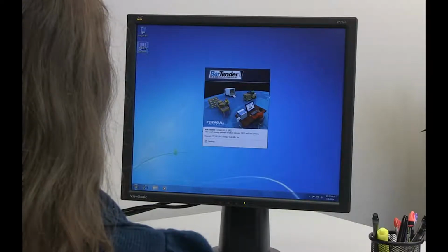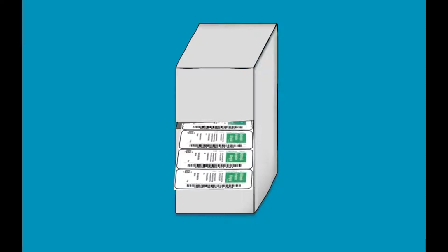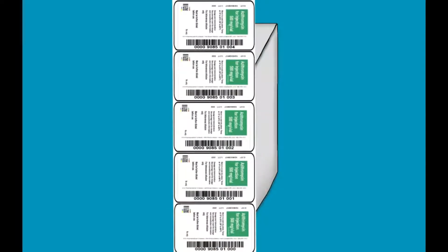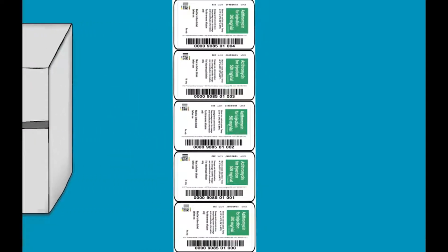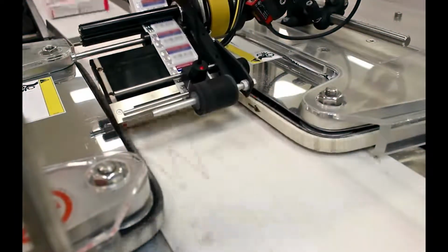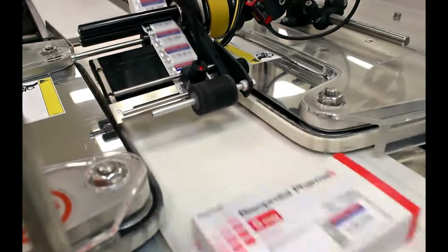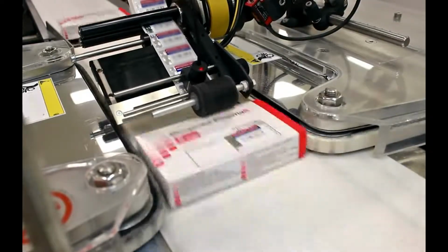In this video, we are going to introduce you to the concept of printing serial numbers. Often when printing labels, the need arises to keep track of the item that is being labeled with a unique identification number that is part of a series. Serial numbers are a series of numbers in either an increasing or decreasing sequence. One method to create this kind of identification number is serialization. Let's look at how BarTender can help you assign serial numbers to your document using its built-in serialization feature.